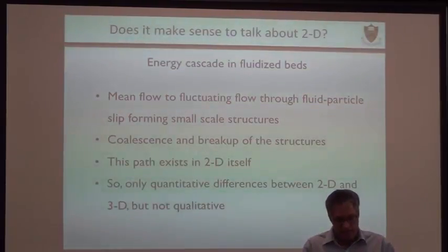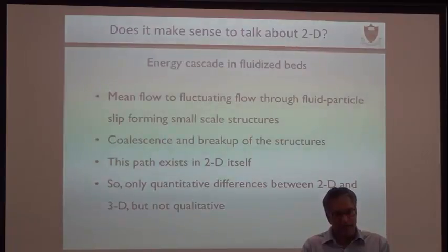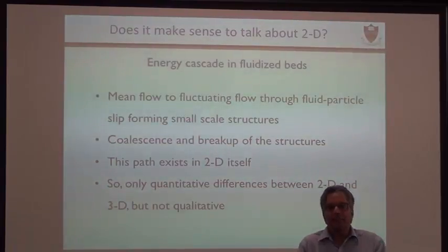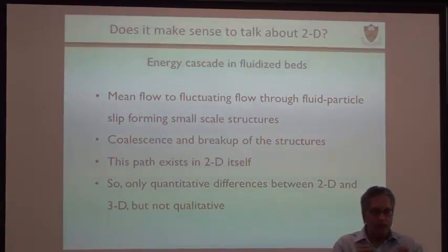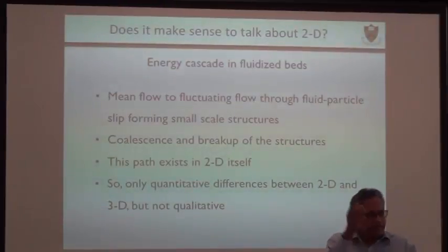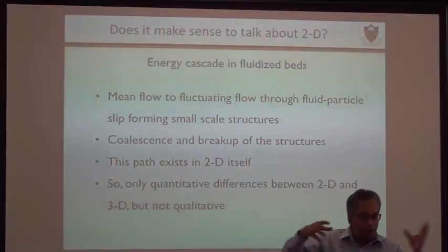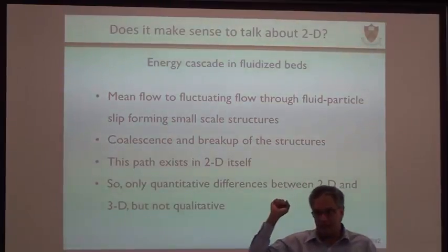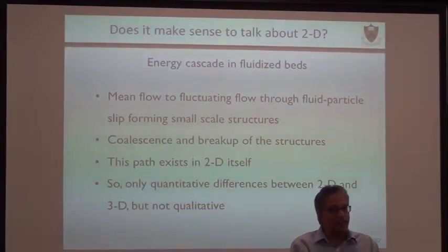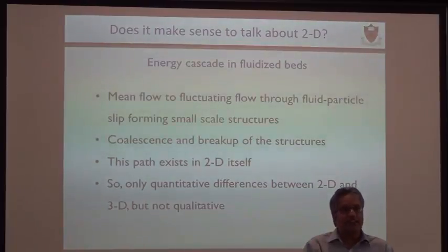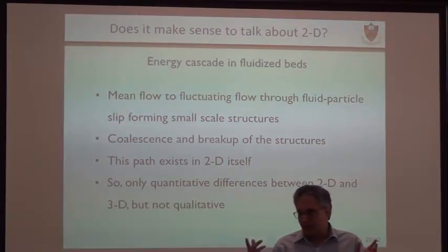What is driving the instability is that on a small scale, the gas and particles don't want to be together. If the particles move away, it makes it easy for the gas. So you first form these small scale flow structures, and then they coalesce to give you larger scale flow structures. And that small scale segregation is even there in 1D, let alone going to 3D.